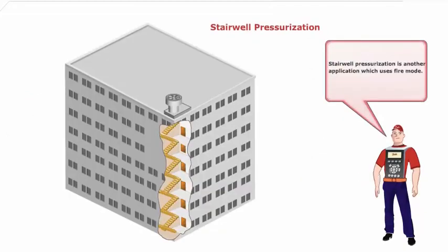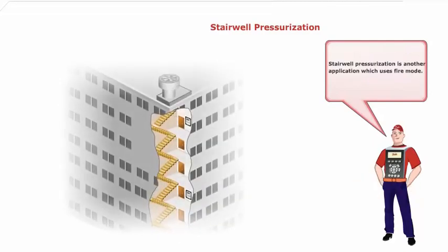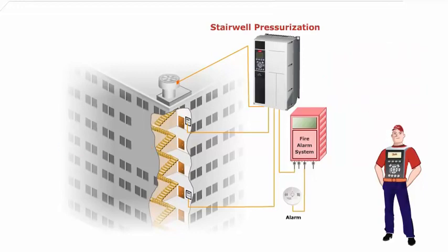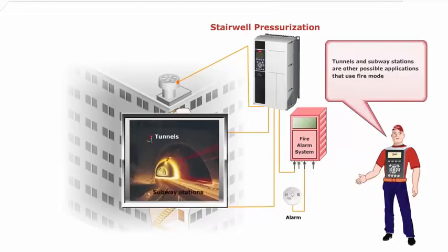Stairwell pressurization is another application which uses fire mode. The purpose of stairwell pressurization is to provide a smoke-free evacuation path during a fire. Smoke must be controlled using a pressure difference across a door. Tunnels and subway stations are other possible applications that use fire mode.